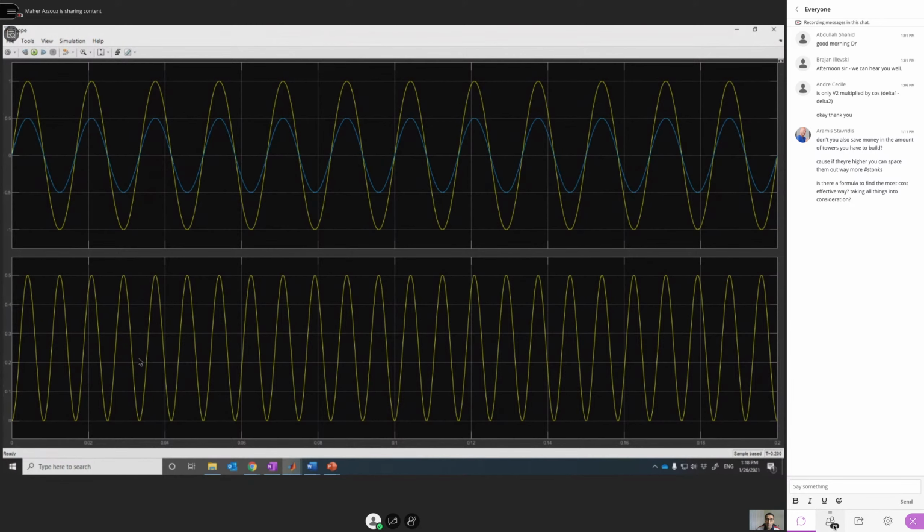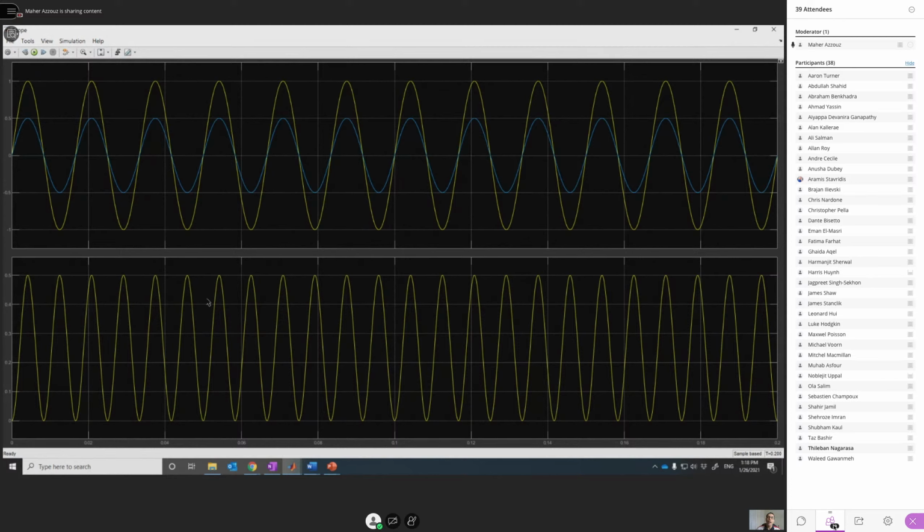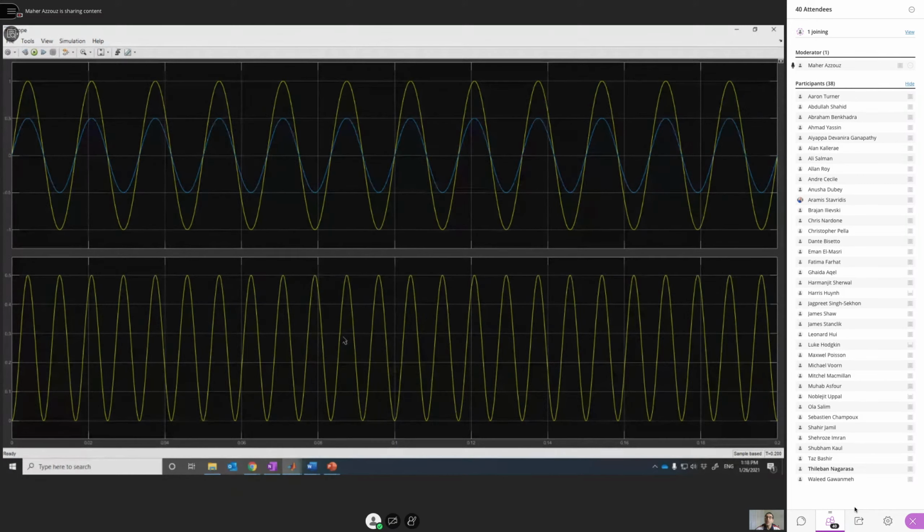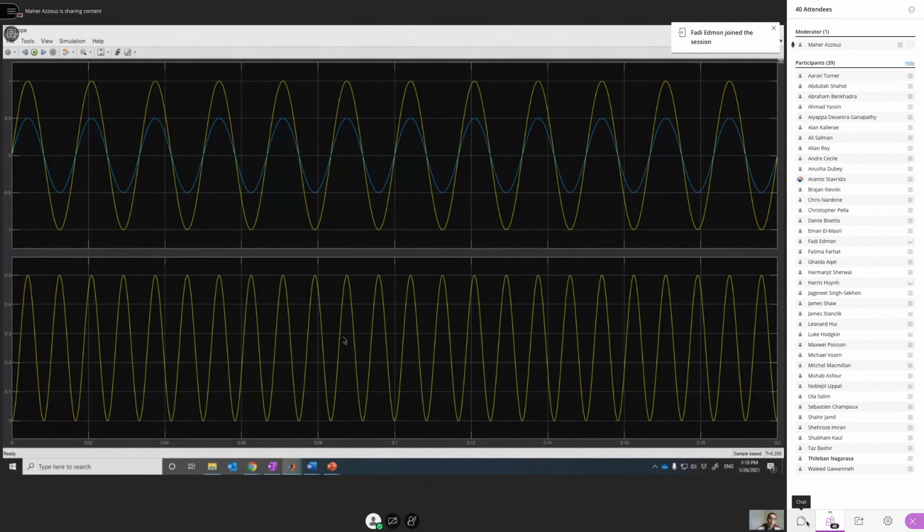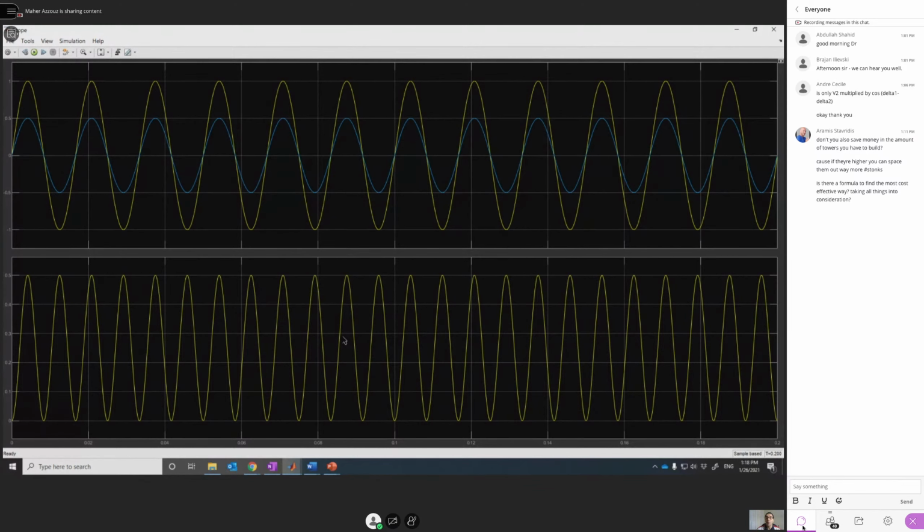The single-phase power is pulsating. It is not constant. We calculated the average power and we named it the active power. This is the power that is responsible for doing the useful work. And we have another component, which is the reactive power. But from what you see here, the active power is oscillating. It is not constant. As a result, the torque generated by the electric motor is not going to be constant. It will be oscillating, and this will create some vibrations. You may not notice those vibrations, but those vibrations are at 60 hertz, and they affect, of course, the lifetime of the machine. So this is for single-phase systems.